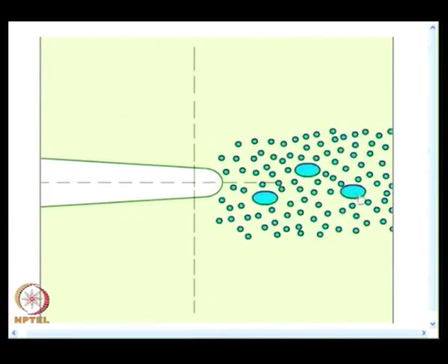Initially, the large particles break, then you have myriads of holes formed, they fail by micro necking, and the crack moves forward. And you see, when you have this micro necking followed by crack propagation, because particles are removed, you find the surface is not smooth, it has valleys and mounds. In fact, you would be able to see that at appropriate magnification in a scanning electron microscope.